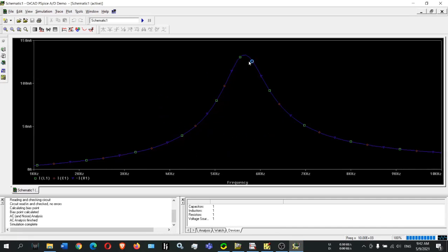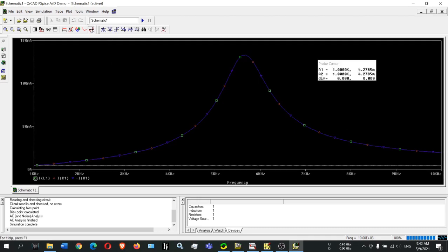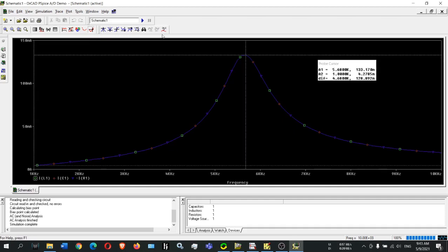So we will need to find the frequency response and the half power frequency from this graph, from the frequency response graph. Then to get the coordinate for the frequency response, which is the peak frequency here, we click the toggle cursor and we choose the peak cursor, and we mark the coordinate here to get the coordinate to appear on the graph here, like this.